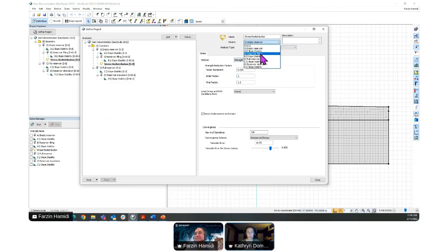If you do have reinforcements in your projects, then consider doing a Sigma W analysis to check the stresses within the domain. Then you could run an FE stress SLOPE W analysis, where the stresses computed in the domain are used in the same method.